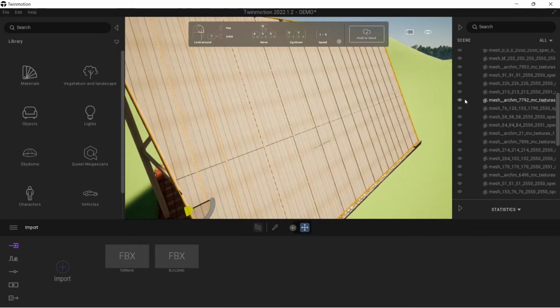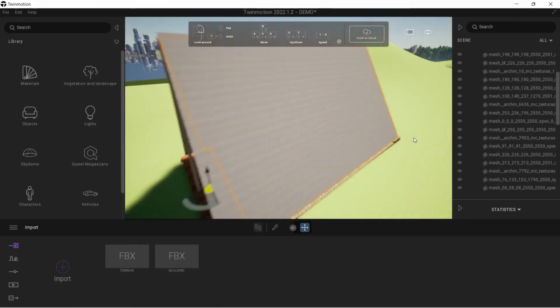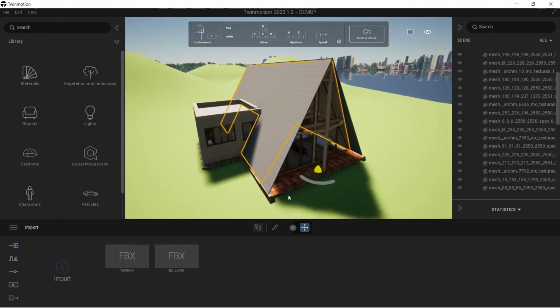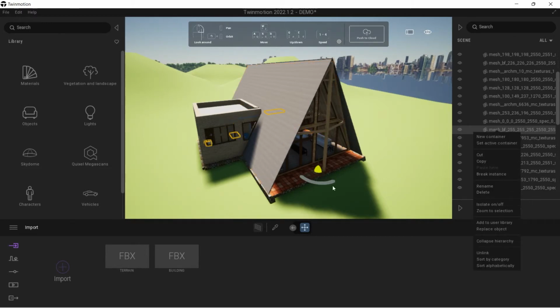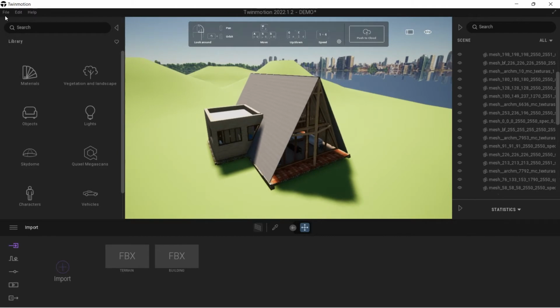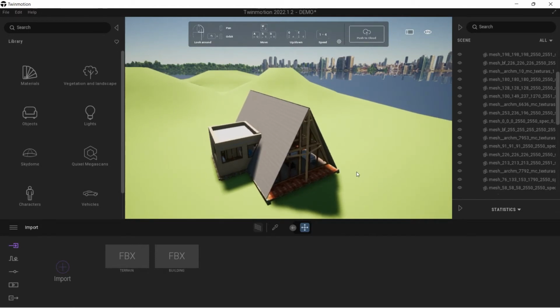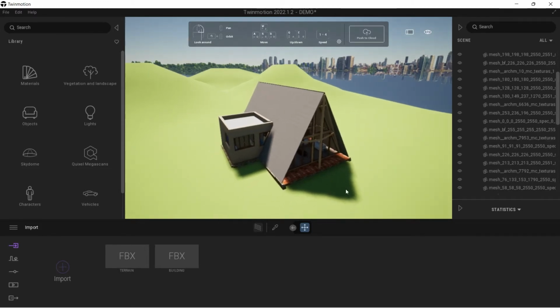but you can also delete this information. Let's suppose that some elements were exported by mistake and you don't want to use that element because it's too big or too complex or you don't need it. You can also delete something here. In our case, the job was well done in the previous phase, so we will use everything that is here. But let's imagine, for example, that the spaces that we didn't export were here. We could deactivate or hide the spaces or delete the spaces depending on the size or the type of this information.